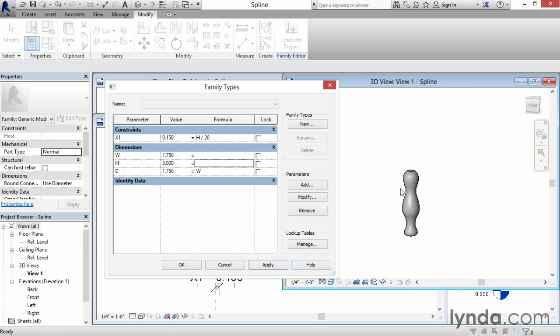To get that really intricate curvature in there and that very complex shape, all we had to do was sketch it out with the spline. If you tried to do the same curve using arcs, you'd need lots of little arcs, and every one of those arcs would require 3 things to constrain them, as we've seen throughout the course. It could be the center, or it could be the arc, or it could be the endpoints or the radius. It could be any of those things, but each arc would need 3 things. That's a lot of reference planes, a lot of trigonometry, a lot of calculation.